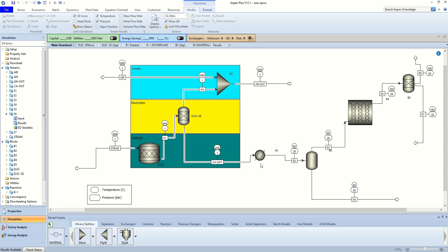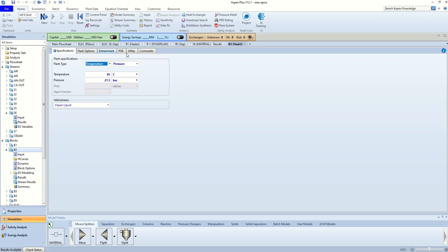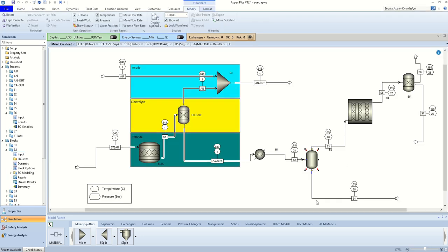So we have provided a heater, but if the pressure was around 5 bars, the pressure is very less in this model, we could have also provided a turbine which could have condensed the water back and provided a hydrogen stream. So now looking at the stream S2, it contains water and hydrogen and some oxygen, at 85 degrees Celsius and 28 bar pressure. So we have provided a flash separator with some pressure drop of around 0.5 bars. As you can see, 27.5, so 0.5 bars of pressure drop has been provided.